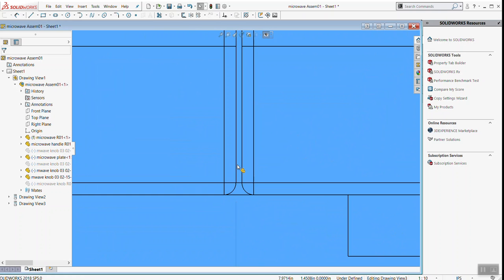If you have a bicycle wheel inside the frame or the fork, there is a certain amount of gap between that wheel and the fork. If that wheel isn't manufactured properly, maybe it's a little off center, you don't want that tire to rub on the edge of the fork. So there is a tolerance of acceptable slop, so to speak, where the wheel will still function as intended, and then there reaches a point where the rubber starts to rub on the edge.